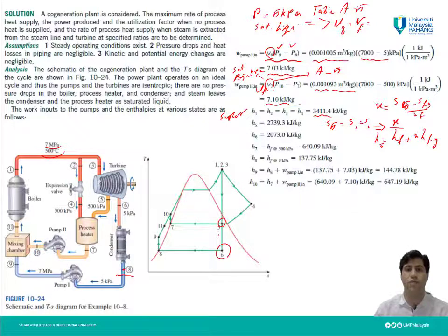If you want to know how to calculate enthalpy for these 2 states, you need to refer to the previous session and review the procedure we used to find the enthalpy and entropy in the wet region. So by using these 2 equations, I'm finding X for H5, and also for state 6: again S6 is equal to S5, equal to S1, for example.